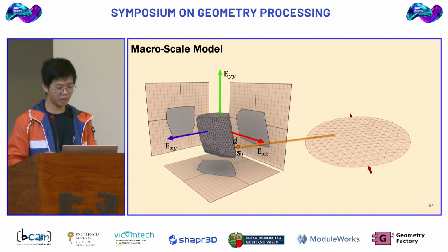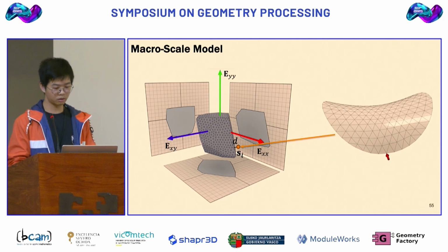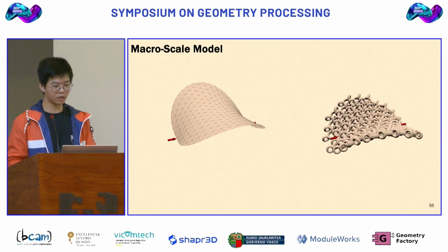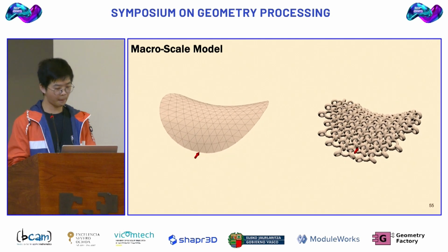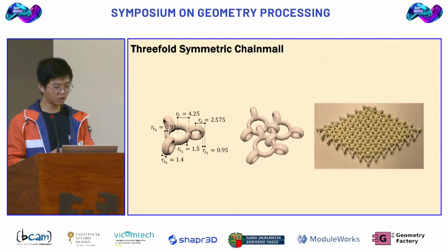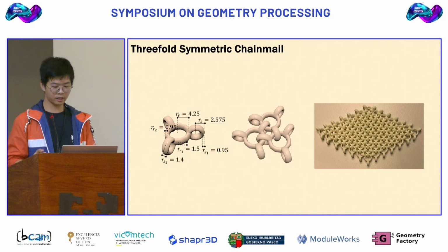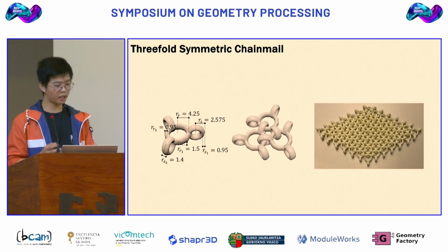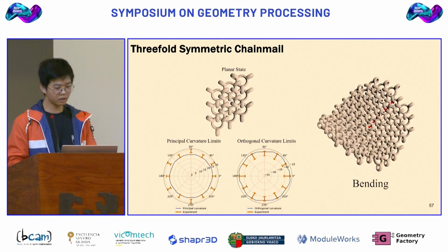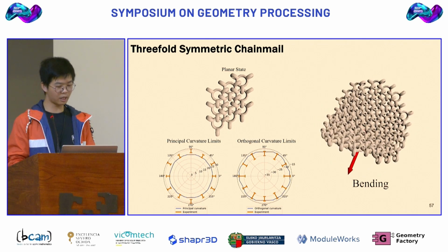And here is the implicit Euler simulation result for the threefold symmetric material. And we can see the macro scale simulation returns a close result to the native scale simulation. And here are some results. The first example is a hexagonal pattern in which each element connects to its 6 immediate neighbors, leading to an overall threefold symmetric structure. The auxetic profile for this material is almost isotropic, as shown in this animation.